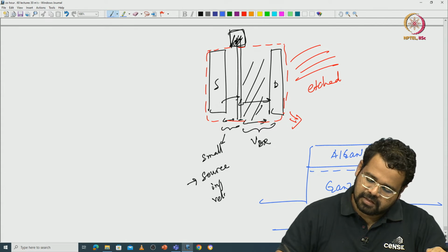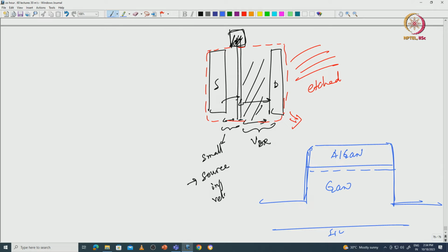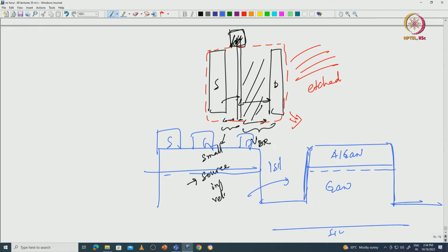this is, suppose, your silicon carbide. I etch it down a couple of 100 nanometers until I get to the iron doped GaN probably, and then this is physically removed. So, the next device will come here again, the source, the gate, the drain. So, this is device to device isolation. This is physical etching using a plasma. You can use a plasma such as BCl3 chlorine plasma. It's called dry etch. A plasma etch is called dry etch.